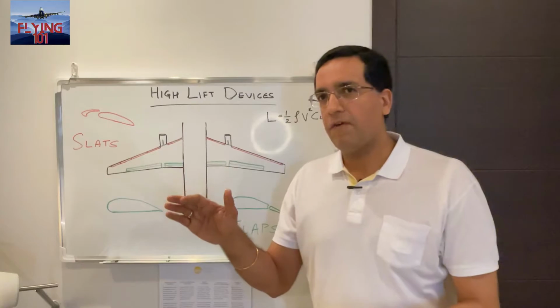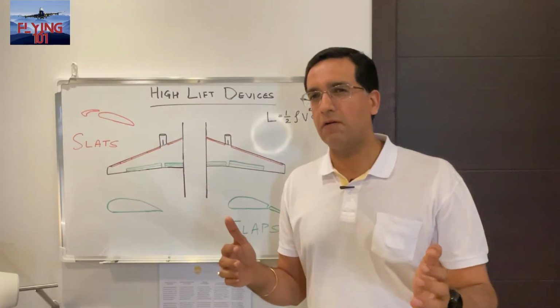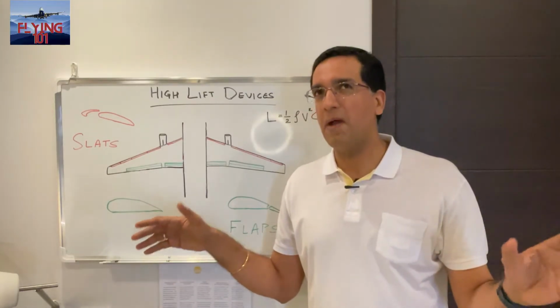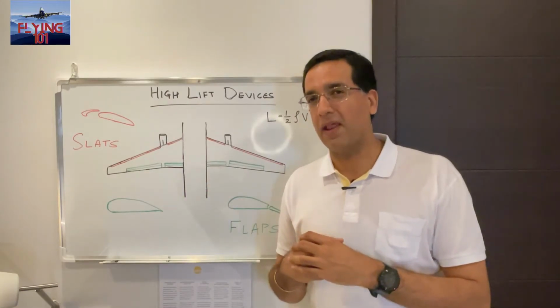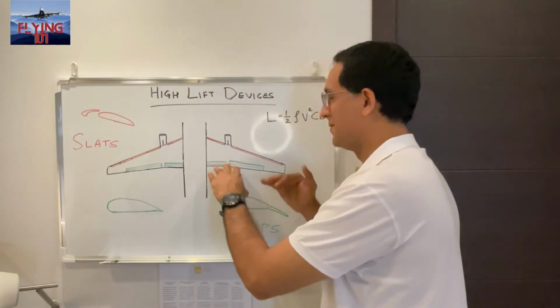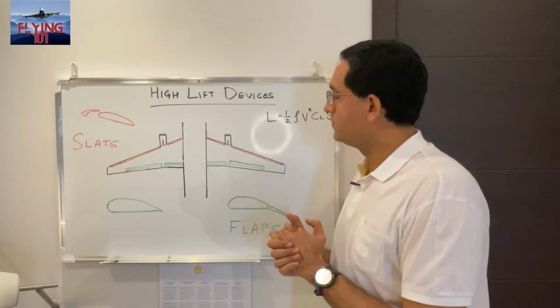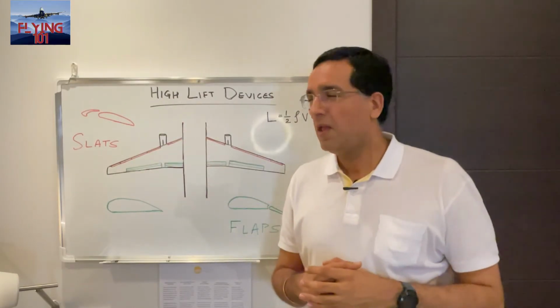Once a plane has taken off and it's reached a certain speed, the flaps will be retracted. For any of you who have been frequent flyers, and if you've sat over the wings, you may have noticed during a takeoff or just before the landing that these surfaces on the trailing edge of the wing would tend to slide out. So, having looked at flaps, now let's understand what slats are.